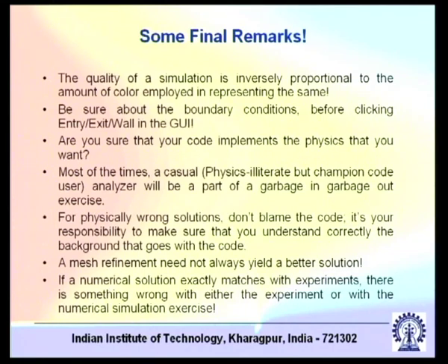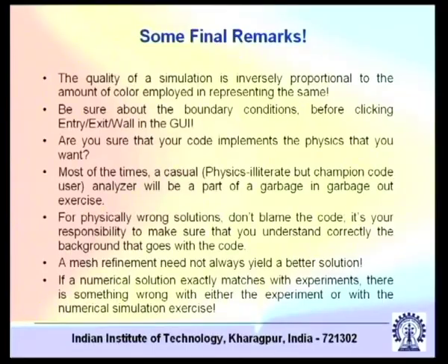So a CFD code fundamentally is what? A CFD code fundamentally is a PDE solver. So it's a coupled PDE solver, so to say. So if the PDEs are possible to be cast in a general conservative form, then only your CFD code can be implemented for the particular problem. If you have equations which do not fall into that category, simply do not use that code. Try to use a different code or develop a code or whatever, but do not use it.